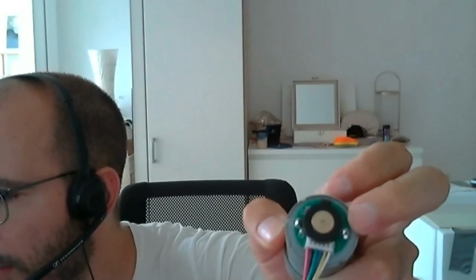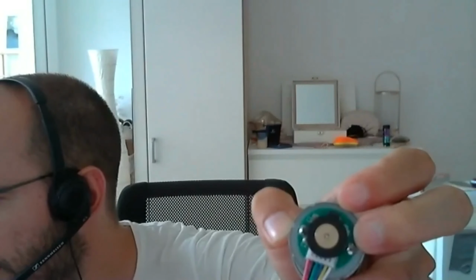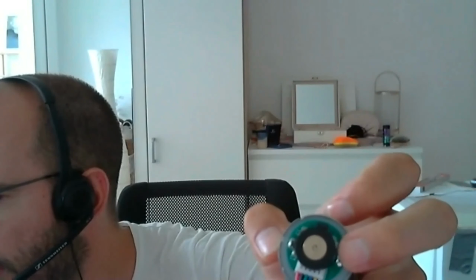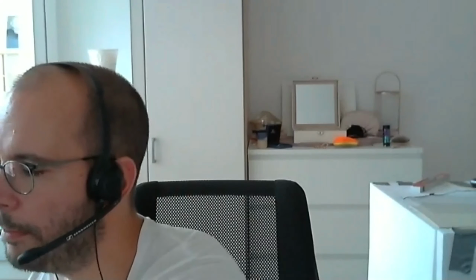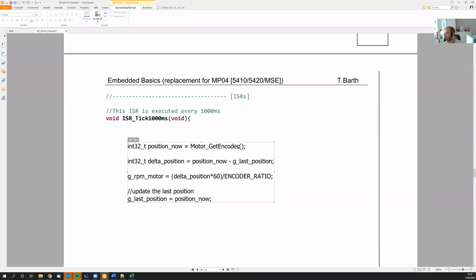On that wheel there are actually 4 contacts, like in that example here. So 1 revolution of that wheel would give you 4 pulses at the sensor. And this is how you would do the math to get from that encoder value back to the position.